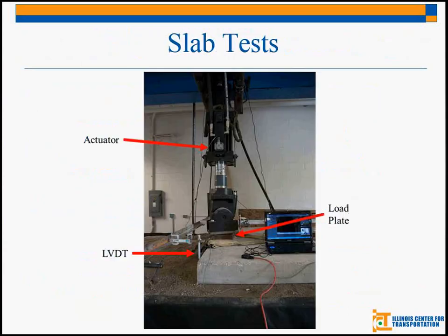And that's all based on slab tests that were done in the summer of 2012, which we've used to correlate back to our fracture properties. How does the actual slab perform in relation to those fracture properties? They found a good correlation between the two, better than the traditional flexural strength, which is the typical method for designing RCC and conventional paving concretes.